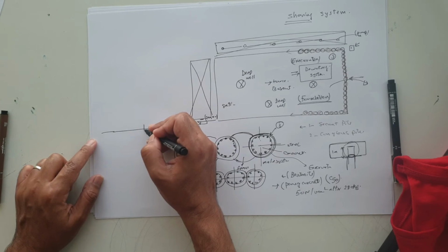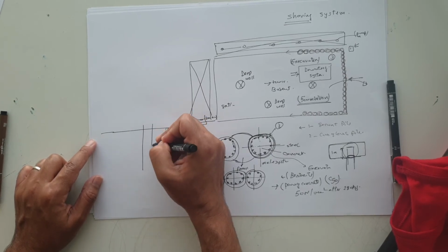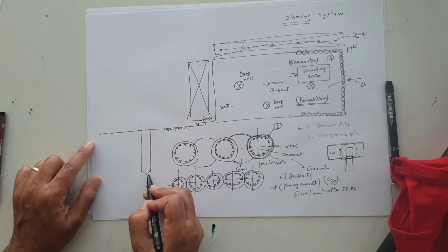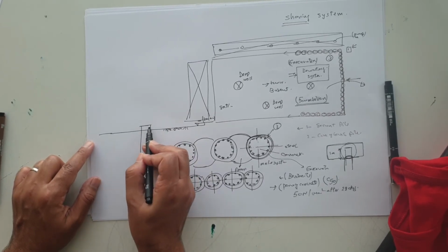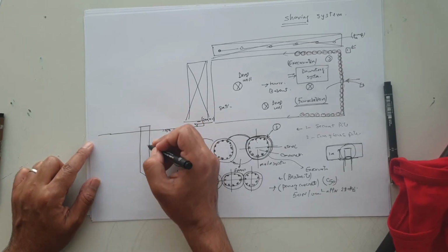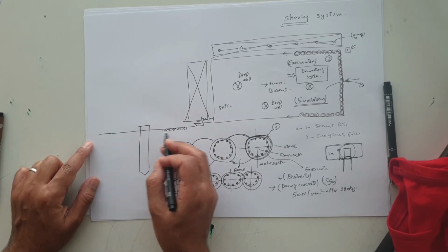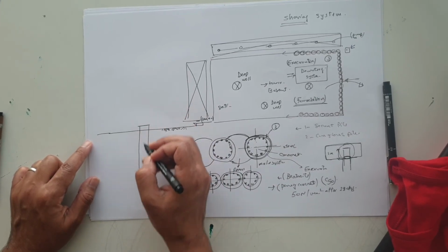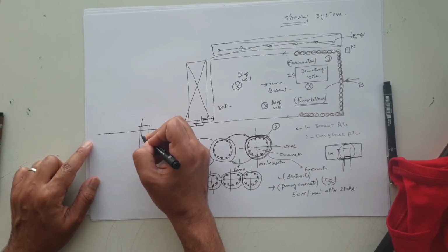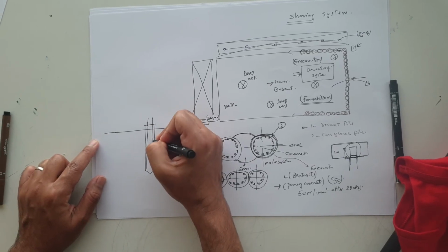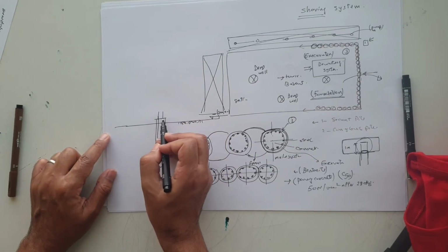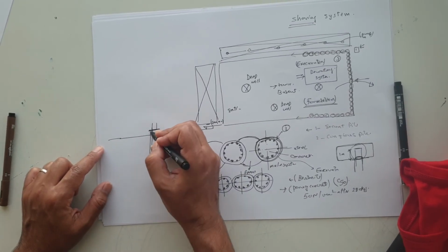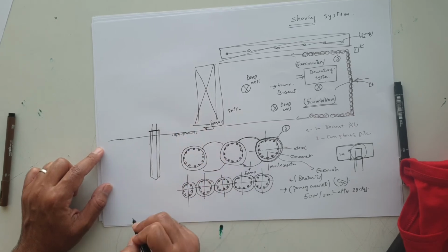And we proceed for the pile system. Like this, we make the same procedure which we made for the shoring excavation: put the bentonite and put the steel inside the pile, then we cut 1 meter, then we properly prepare the surface of the pile like this.